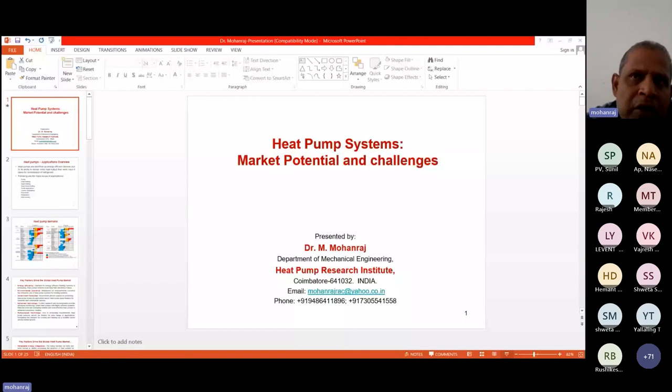After this, hydrofluoroolefins came into the picture. Hydrofluoroolefins are recommended as an alternative option to R134A. They have been proved to have similar thermophysical and thermodynamic properties, and they are a best option with a global warming potential of less than 4. It's around 4. They're saying it is the best option to replace R134A.